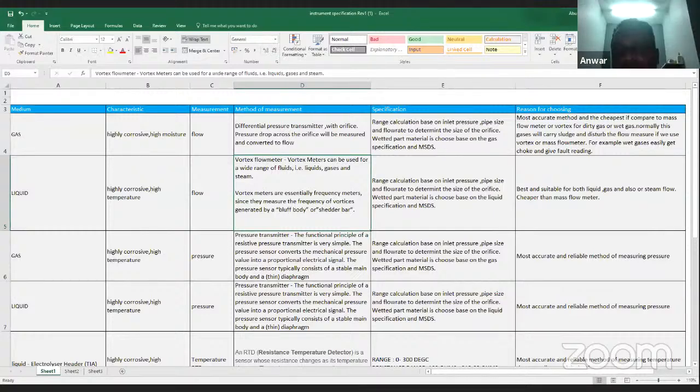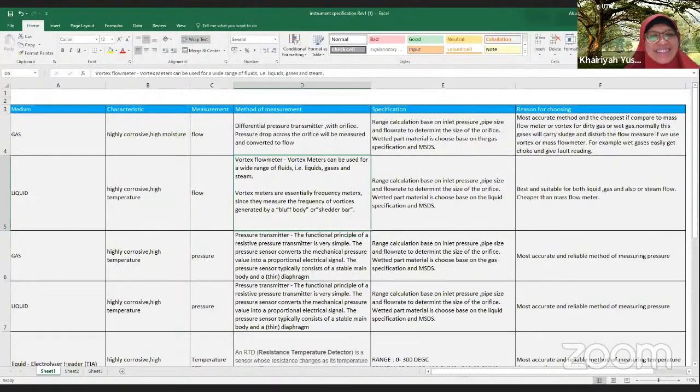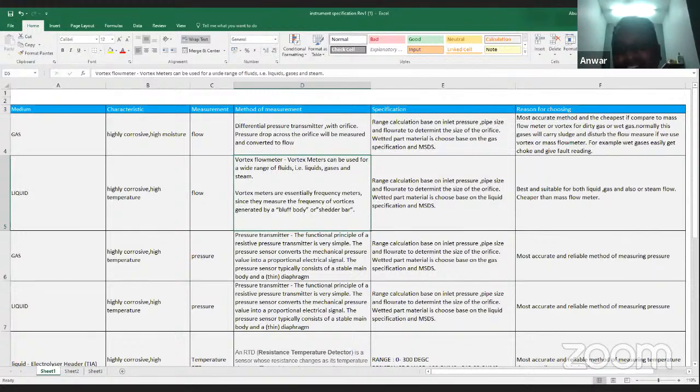Okay. Feasibility involves cost and resources, so everything should be determined so that you have the right frequency. For instrumentation calibration, minimally it is 6 months, from what I have experienced.